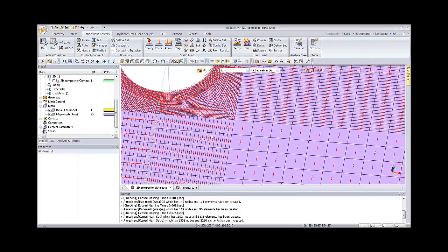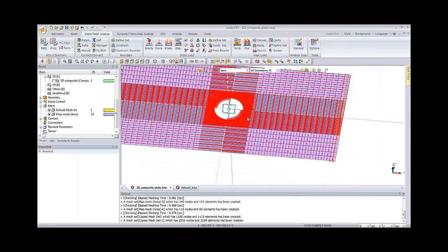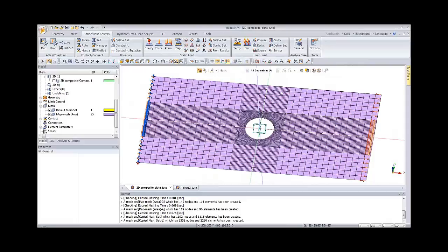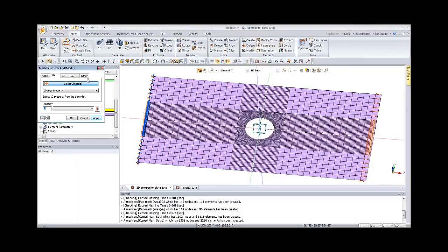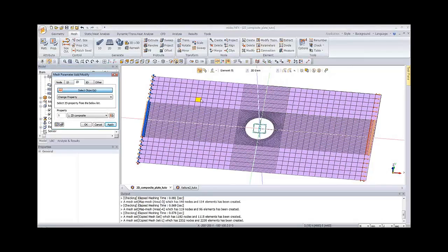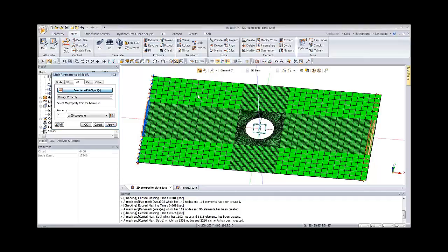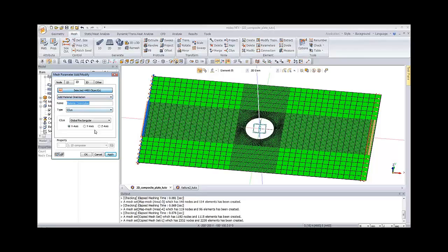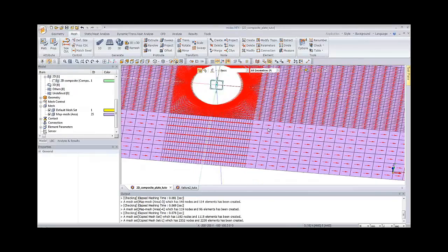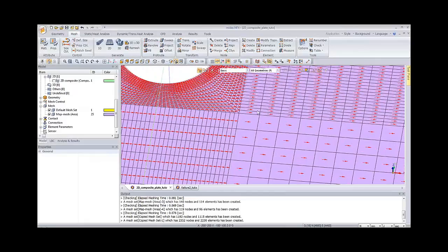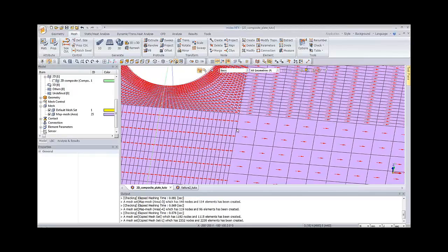So in order to change that, you have to go in the Mesh tab, Parameters, 2D, Parameters, and here select all the mesh. And you have Add Material Orientation. So here I will put all the elements in the X axis, so you can preview. Okay. And if I activate it again, you see that now it's correctly set. So all the orientation of the material is in the same direction as the load. Okay, I activate that again.